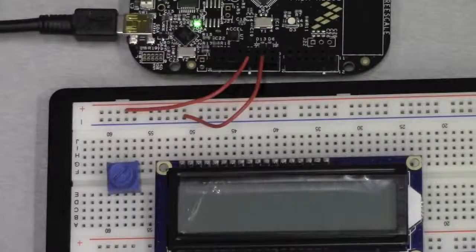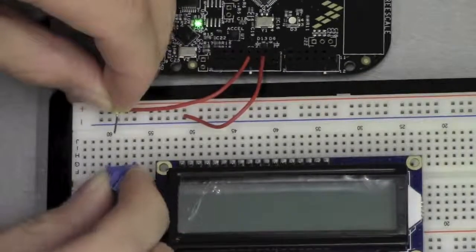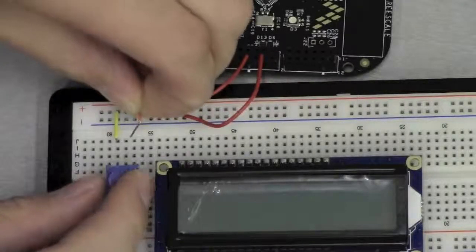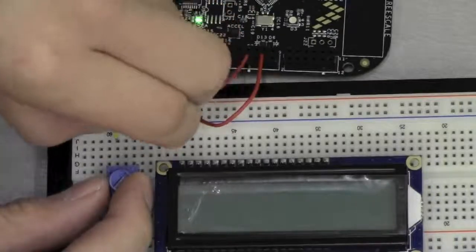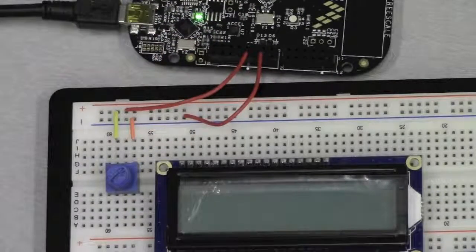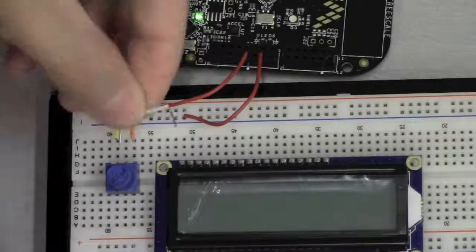Okay, so the potentiometer needs the 5 volt and the 0 volt supply, so we're going to connect the power line to one of the ends of the potentiometer. We'll connect it here, and then the other end needs ground, so we'll connect ground to the next one. Once we have that set up, now we need to connect the middle pin, which is the one that gives the variable voltage, to pin 3, which is V out. So we're going to go ahead and do that.